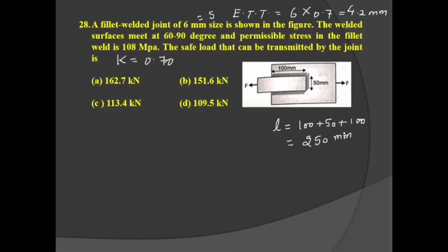So the safe load we have to calculate. P safe is equal to L effective into effective throat thickness into the stress available, that is 108 megapascal.